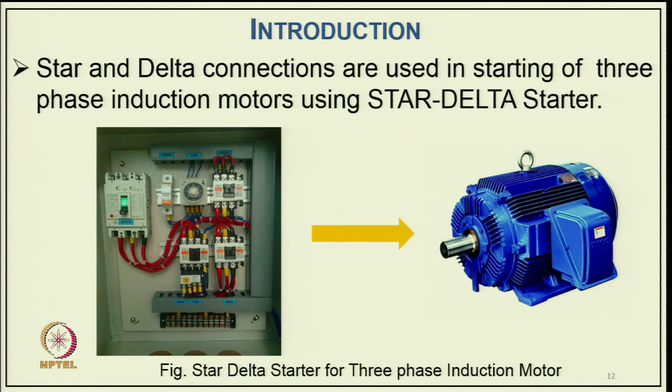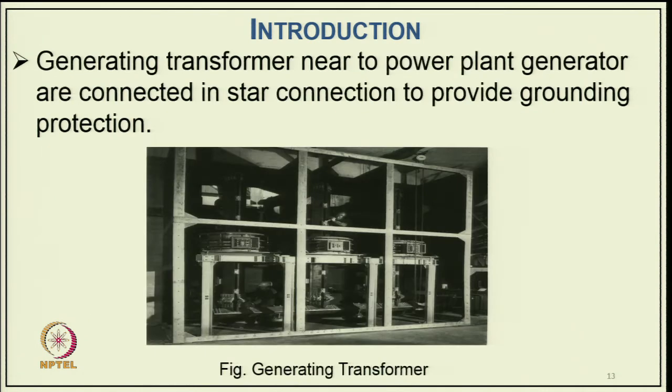And once the motor is started, either with a time delay or with the current, depending on the current limit, it is converted into delta, finally running the motor at full load. Most of these starters are now automatic type star delta starters with proper protection. Earlier, of course, they were manual. Initially you had to connect in star connection and finally in delta, but both these windings are virtually connected by this proper connection, you can call it an electromagnetic switch. We connect in star as well as in delta, depending on whether the motor is starting or finally running.